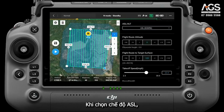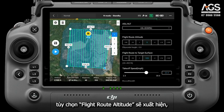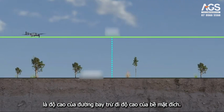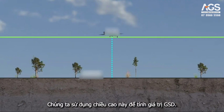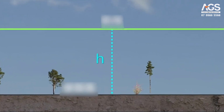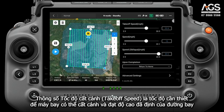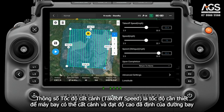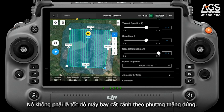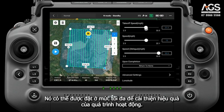When ASL is selected, the flight route altitude option appears. It is equal to the height of the flight route minus the height of the target surface. We use this height to calculate the GSD value. Takeoff speed is the flight speed at which the aircraft reaches the height of the route, but not entering the route. It is not the speed at which the aircraft takes off vertically. It can be set to the maximum to improve efficiency.